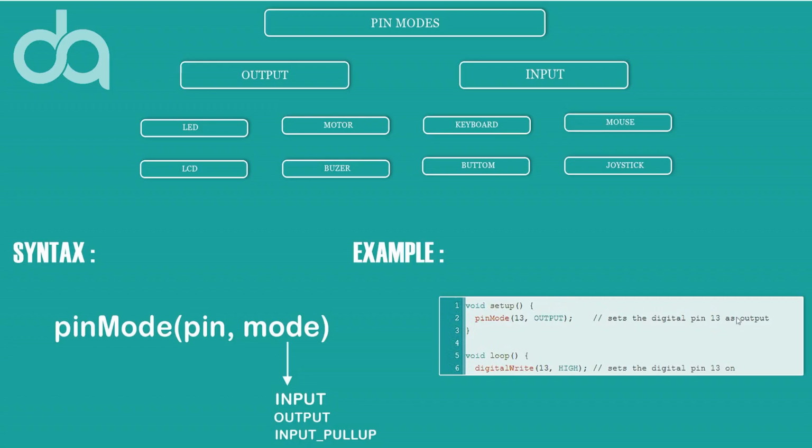And there is also an important point that instead of using an external resistor, you can use the internal resistor of Arduino with the command of INPUT_PULLUP. And that's it. I will create the video for you and put it in the description of this video.